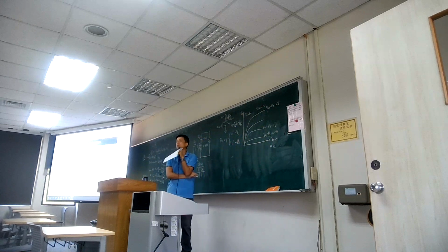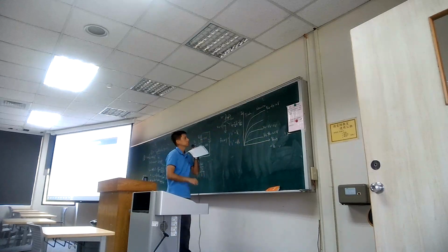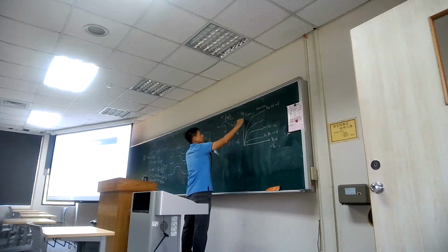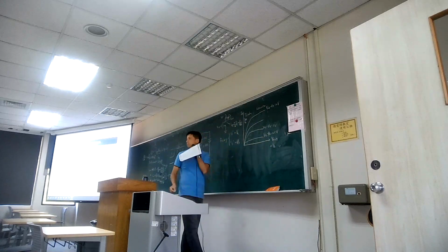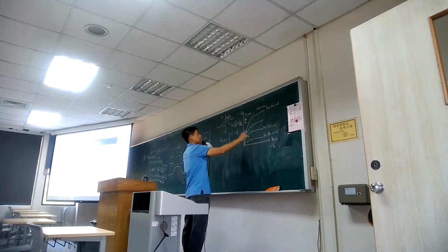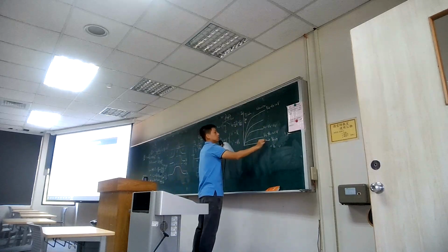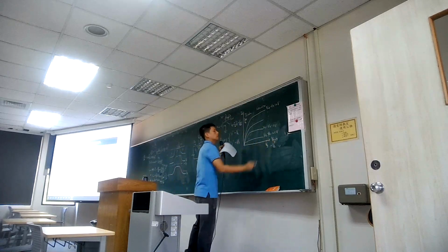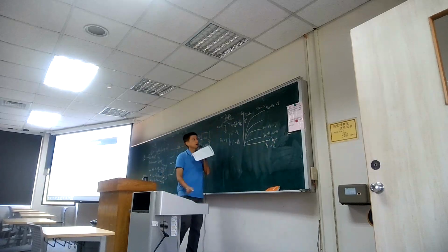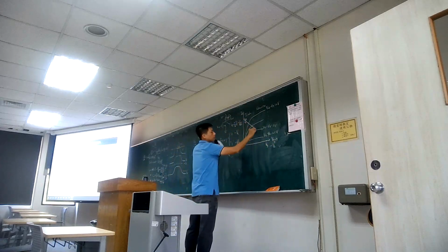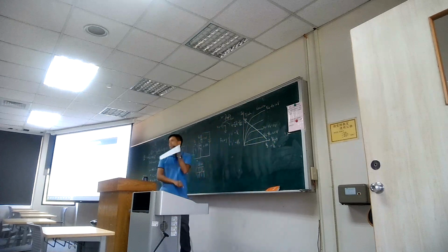So you can think that maybe you just draw points. It is a linear relationship. If you consider VD equals 0, what happened here is that you get output is 0. The ID equals VDD over RD. Okay. And how about if you consider ID equals 0, VDD equals V out? So you get two boundary conditions. Okay. Once you get these two boundary conditions, it should be like a slope here.